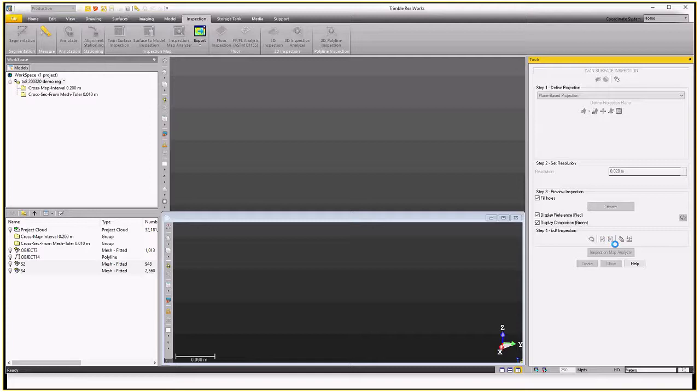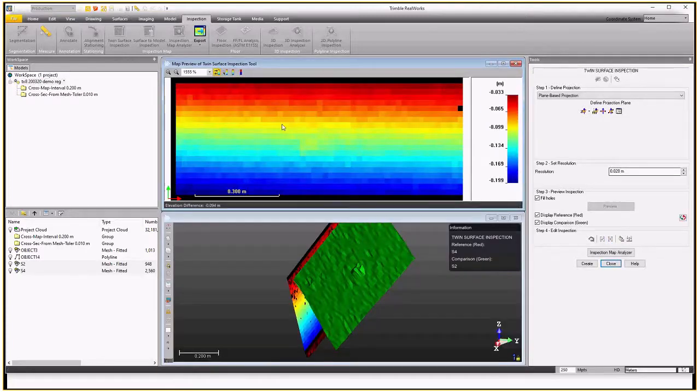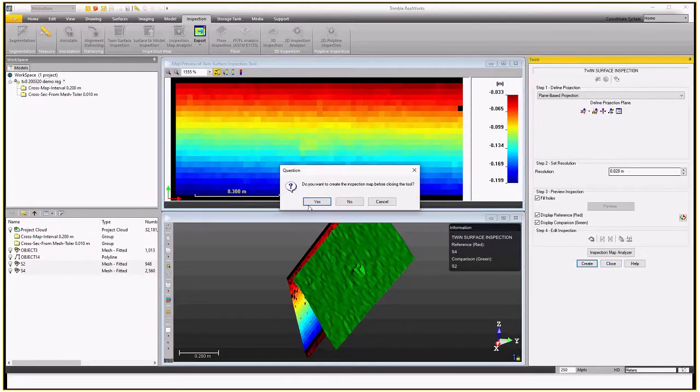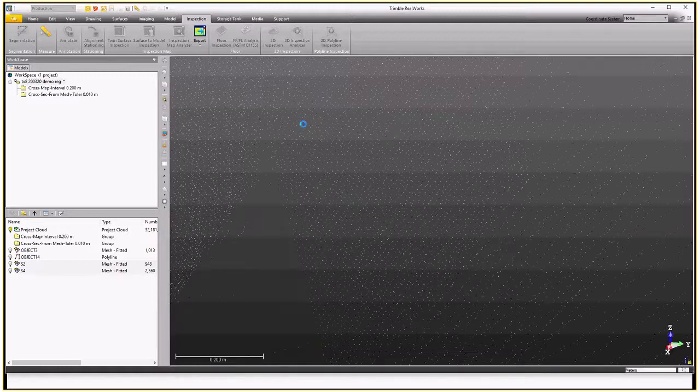So the inspection tools, we also have floor flatness tools, which I won't go into here today due to time constraints basically, but they're pretty straightforward. We put a grid over the floor, we can nominate tolerances, and it'll give us a heat map again, and also a grid showing the differences between the RL that we've chosen and the point on the, well, commonly slabs, and we can export a report as well for that. So they're the inspection tools.